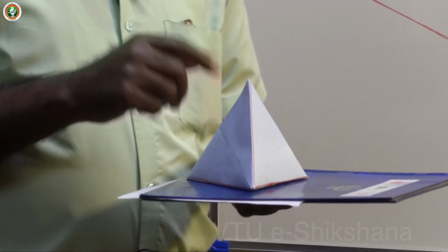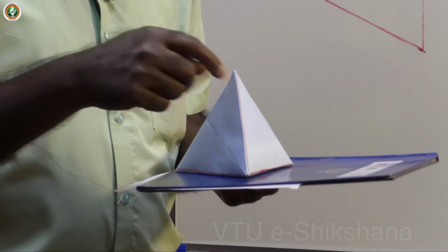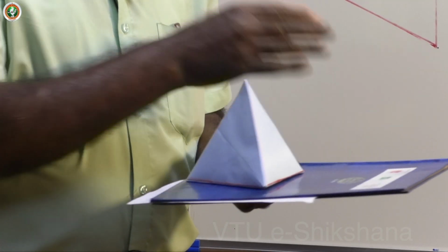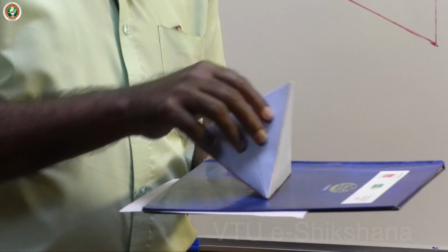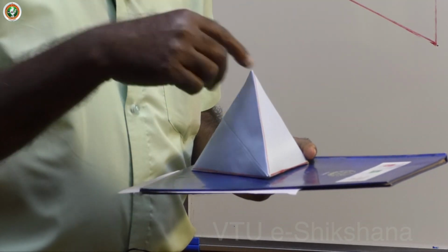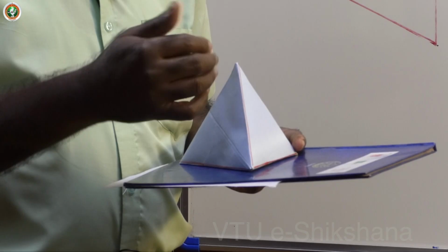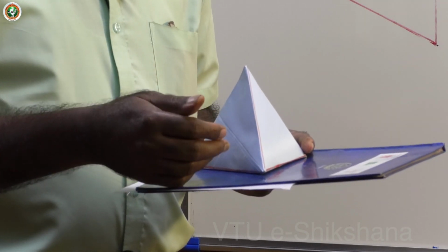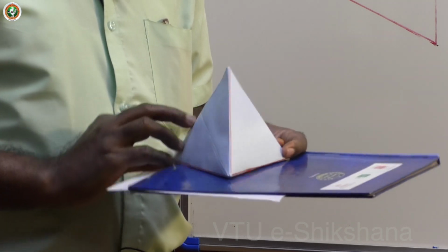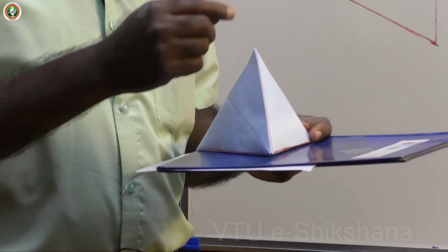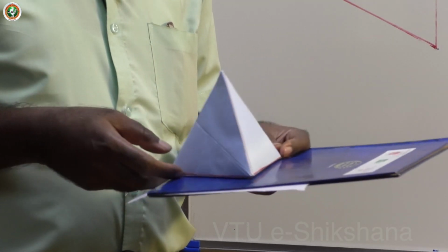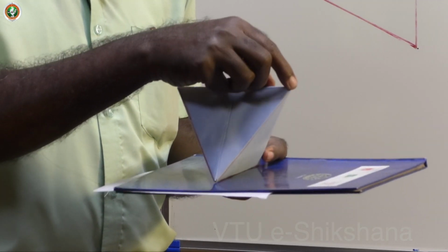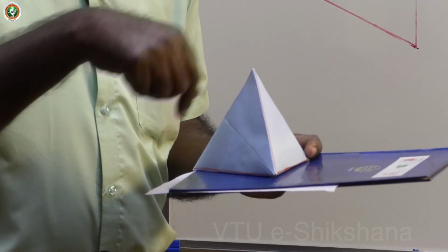So this is the first position because he says a side on HP. The side to be placed on HP is always perpendicular to what? VP. Now the face is inclined, which means the axis is also inclined. It is like the pyramids, where the slant face is inclined at some degree to HP, so the axis also assumes a particular inclination. So first position, second position. If you assume the axis, considering this as the base center and this as the axis, then that is also inclined. If it is inclined, make it perpendicular to HP so that you get the true shape on HP.